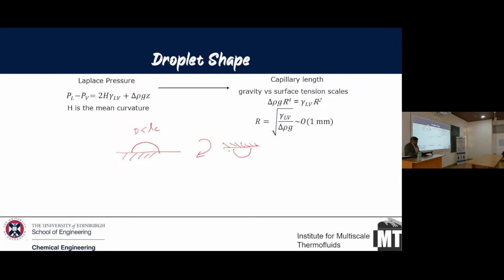In fact, when you have a pendant droplet like this, we find that if the vapor is denser than the surrounding fluid, the vapor actually goes in this way as the droplet evaporates. And there is a recirculation zone which is set up in the droplet, which will not be possible if you didn't have gravity, even if the droplet is much smaller than the capillary length. Okay, so there are special considerations you look at.